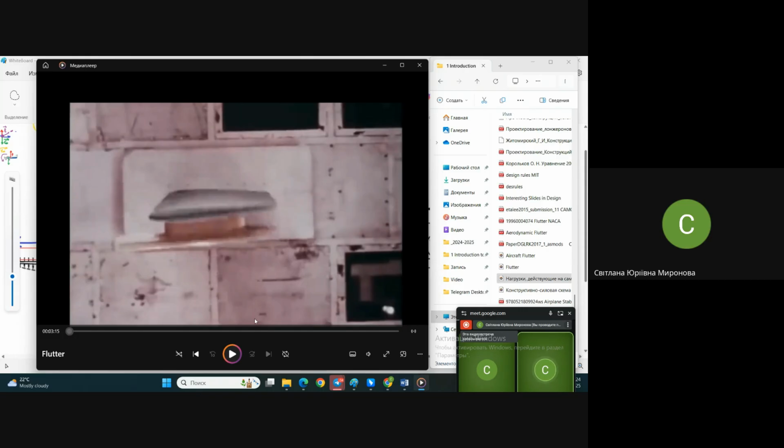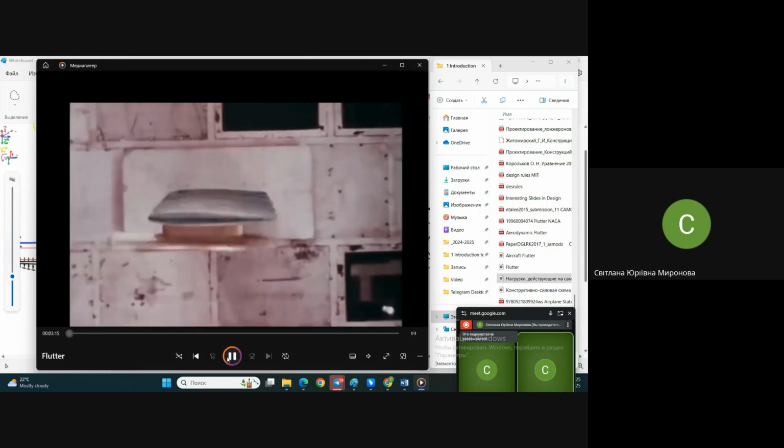Now, what do we see? It's a so-called weight balancer, an additional device, additional weight, unnecessary in terms of aerodynamics or the purpose of the aircraft. But look, people study how additional weighting on the wing, additional mass added to the wing, may counteract flutter. Let's watch once again. You see some even missiles.